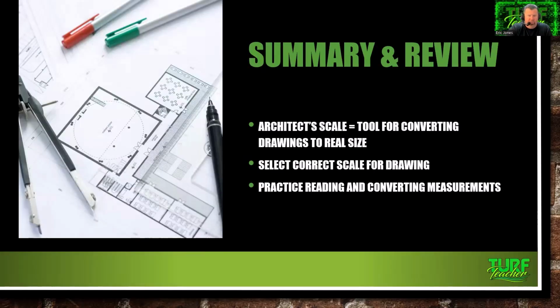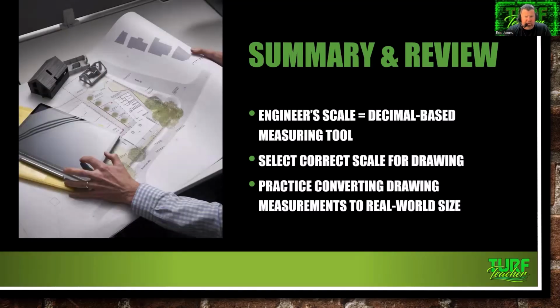And so, summary and review: architect scale, a tool for converting drawings to real size. Select the correct scale for the drawing. Practice reading and converting your measurements. With the engineer scale, it's a decimal-based measuring tool. Select the correct scale for the drawing. Practice converting drawing measurements to real-world size.